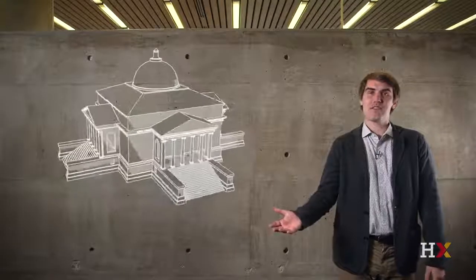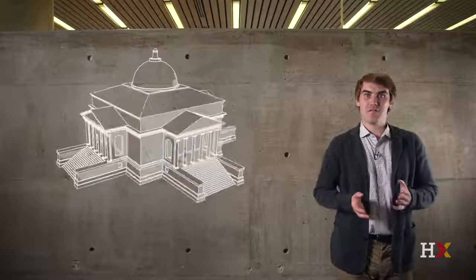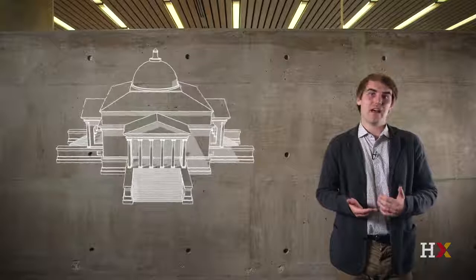We'll begin with what we call the orthographic drawings. They're called orthographic because they're orthogonal or perpendicular to each other, and these are the major drawings that are made to represent buildings abstractly. They are the plan, the section, and the elevation. We're going to use the Villa Rotonda, which is a late Renaissance villa designed by Andrea Palladio, which we can see here, to discuss these different kinds of orthographic drawings. And we're going to start with the plan.